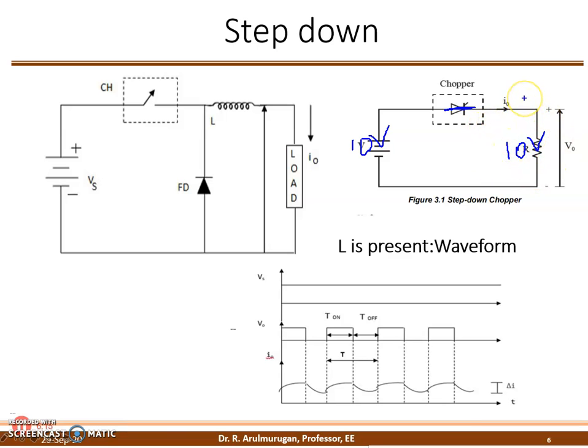Then what is the output waveform? Did you see my DC chopper practical video experiment? If you have seen that, you will know the output waveform is a square wave. The output is pulsating DC, a pulsating on-off DC. Why is pulsating DC produced? Because there is no filter and no inductance used. That's why it produces pulsating DC.